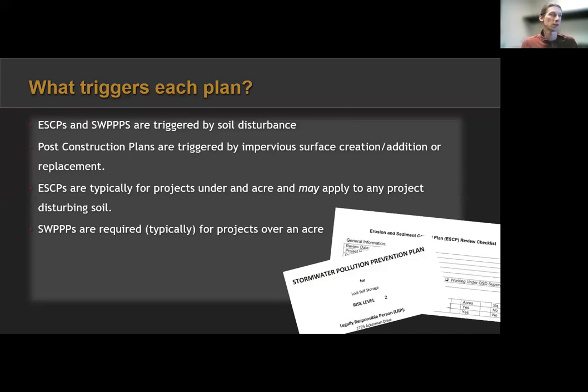Erosion sediment control plans, I mentioned this, are triggered by municipal ordinances, and they are required by the Phase 2 MS4 permit. But the SWPPPs, we don't require them per se. We're not the ones who permit SWPPPs. That's done through the state on their permitting portal, and you need to develop and upload a SWPPP on SMARTS pursuant to the construction general permit standards.